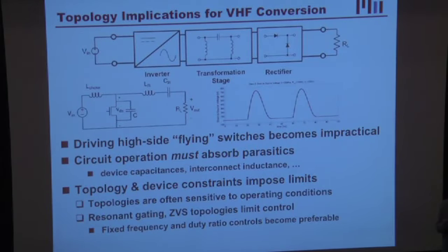So what are the implications of this in terms of the circuit design? First of all, there are a lot of implications. We can't use the conventional kinds of topologies that people use in these applications because they don't meet the constraints. So for example, once you get to sufficiently high frequencies, you can't use topologies where the control ports of your transistors are at flying nodes, right?